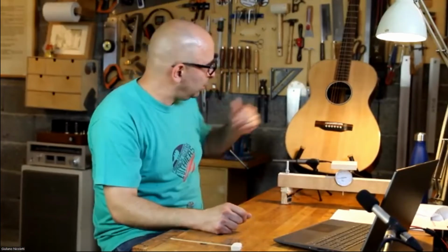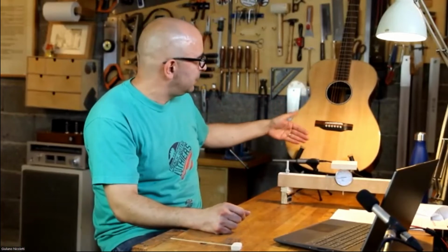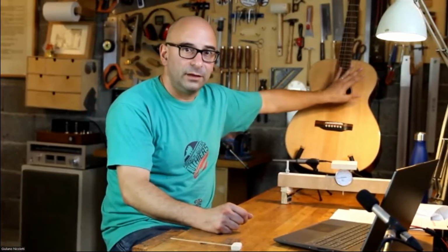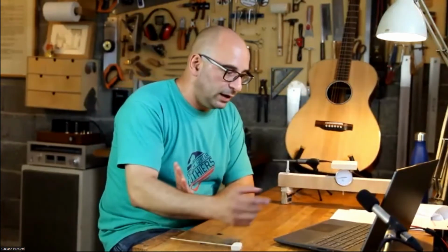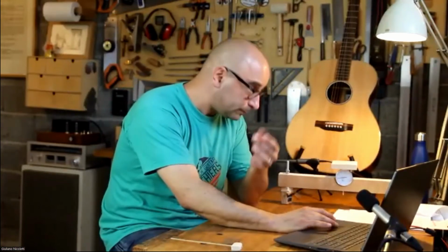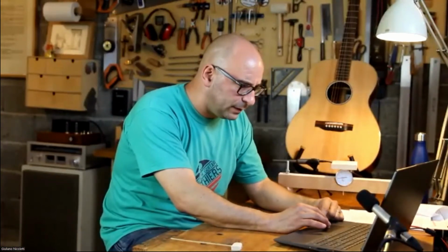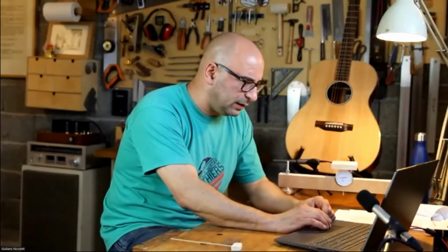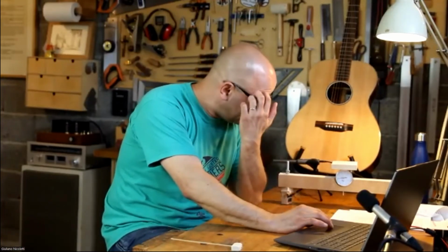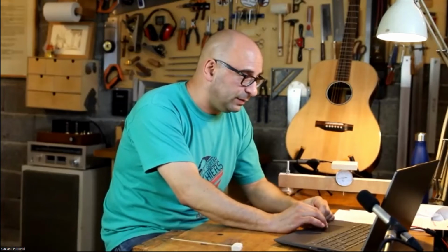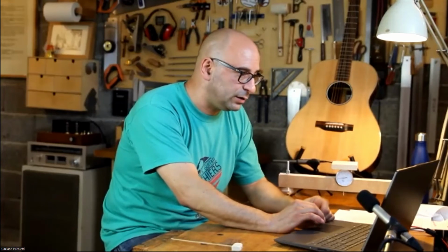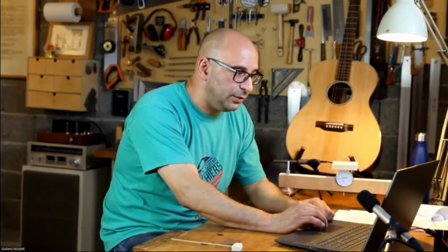And once you know the compliance, you measure the resonance frequency. There is very simple math to calculate the equivalent mass, the mass of the resonance system. And if you need, I have this Excel file that I can share, of course, where you just insert the mass, the measured deflection, and the natural frequency, and you get the equivalent mass and the monopole mobility parameter.